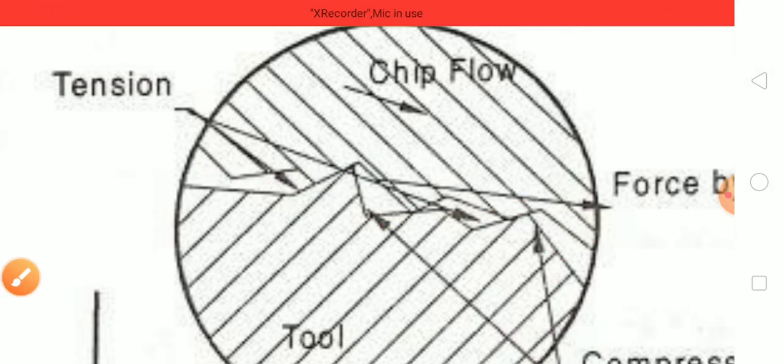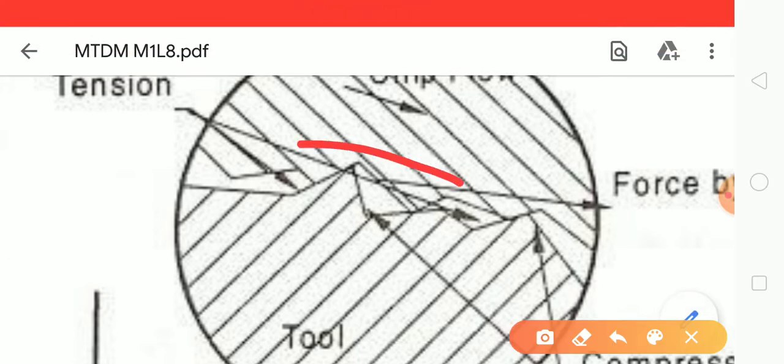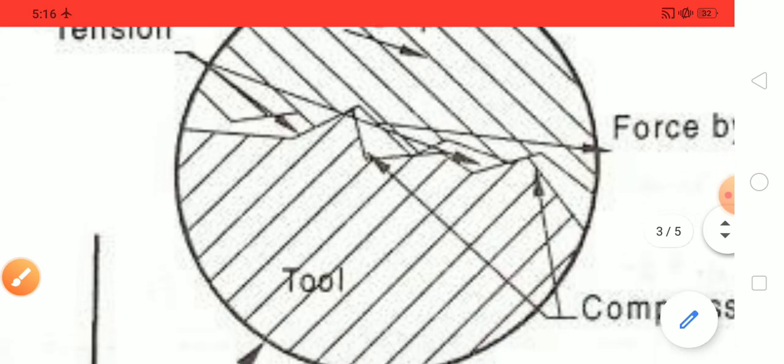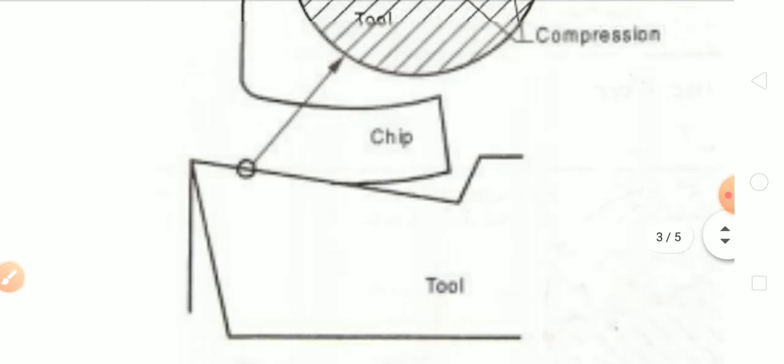Like first, under compression, edges will be formed and chipped off during the machining action, and again while applying compressive force there will be edges formed which are also cut off by the machining action, and this process continues to form many cycles, which in turn fail the material by the fatigue force formed in between the surfaces. So that is fatigue wear.